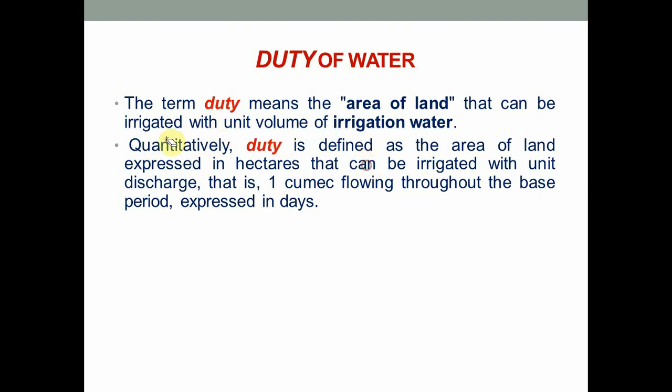Now quantitatively, duty is defined as the area of land expressed in hectares that can be irrigated with unit discharge, that is 1 cumec or 1 meter cube per second, flowing throughout the base period expressed in days.